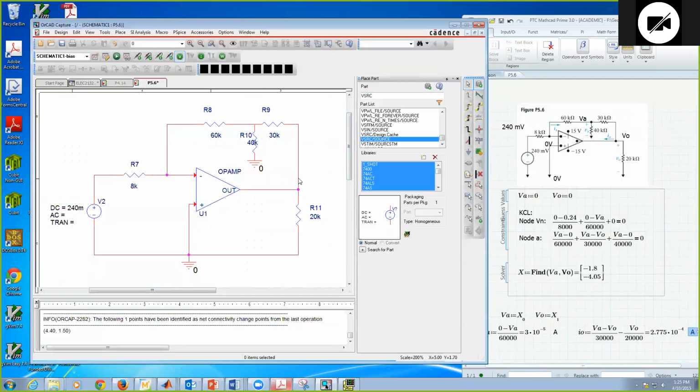So now I have all my components with the proper values on them for the resistances. Okay, so let's save this. And now that I've built the circuit, I can check my connection. So this is connected to ground. These are all grounds. This is 15045. So all these are common node, and so on. I just double check to make sure that all my connections are correct.